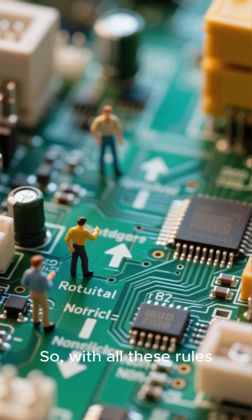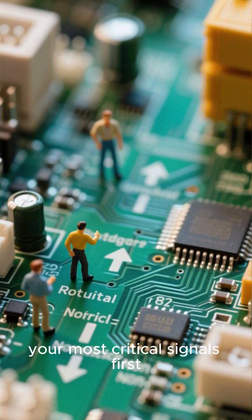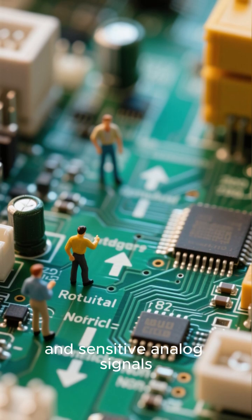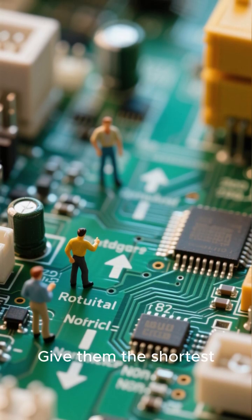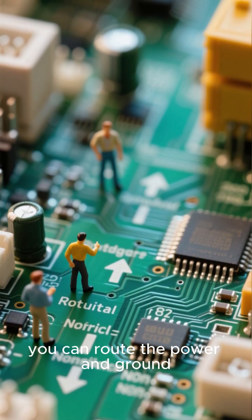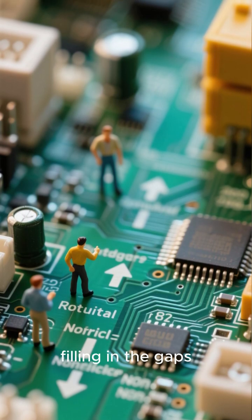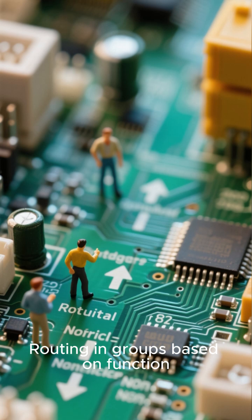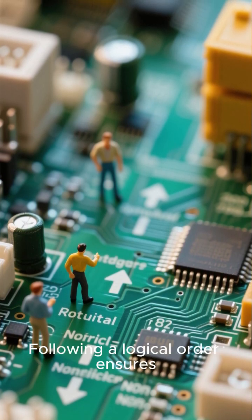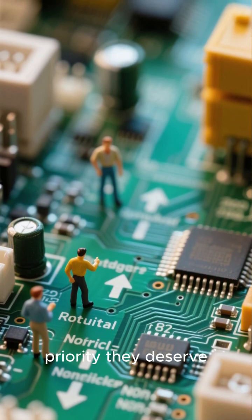So, with all these rules, where do you start? You need a routing order. Always route your most critical signals first. This includes clocks, high-speed data lines, and sensitive analog signals. Give them the shortest, cleanest paths possible. Once they're locked in, you can route the power and ground distribution network. After that, move on to less critical signals, filling in the gaps. Routing in groups based on function can also help keep things organized and minimize crosstalk. Following a logical order ensures that your most important signals get the priority they deserve.